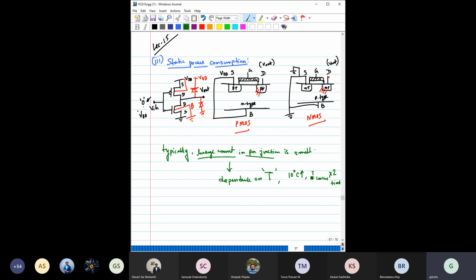And when you are operating a transistor, there will be some power dissipation, and the dissipated power would be radiated as heat, which will raise the device temperature. So the junction temperature would not be at room temperature, but at a higher temperature. If the temperature rises by 60 degrees, you can imagine how many times you have to multiply to get the leakage current.